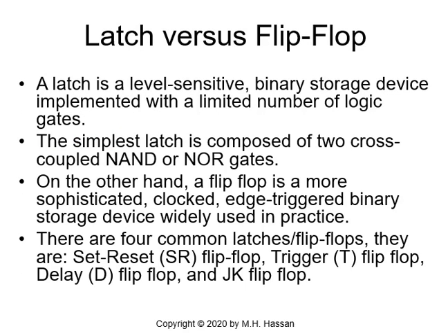What's a latch, and what's the difference between a latch and a flip-flop? A latch is a level-sensitive binary storage device implemented with a limited number of logic gates. It may or may not have a clock. The simplest latch is composed of 2 cross-coupled NAND or NOR gates.